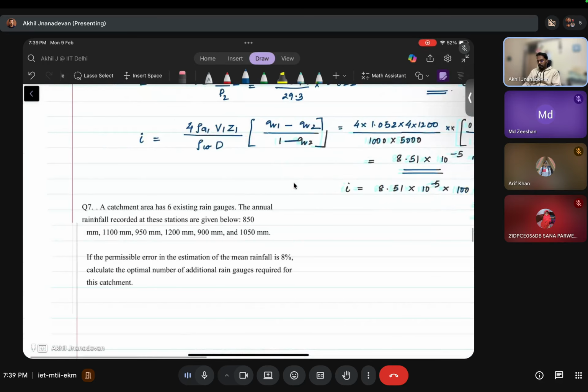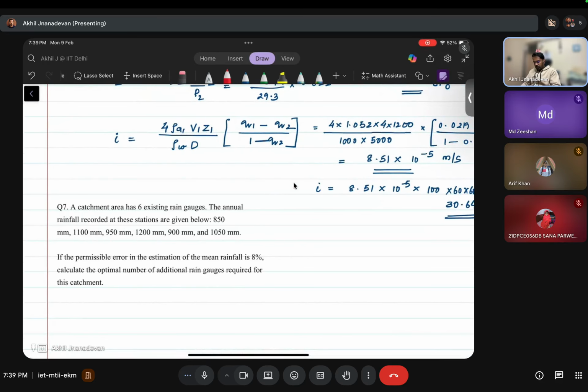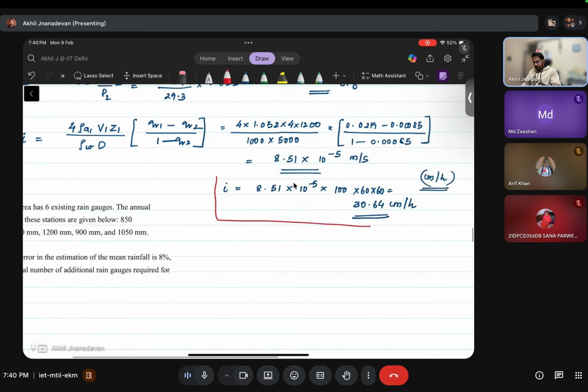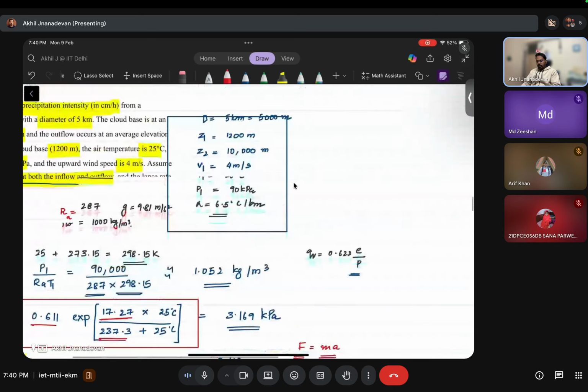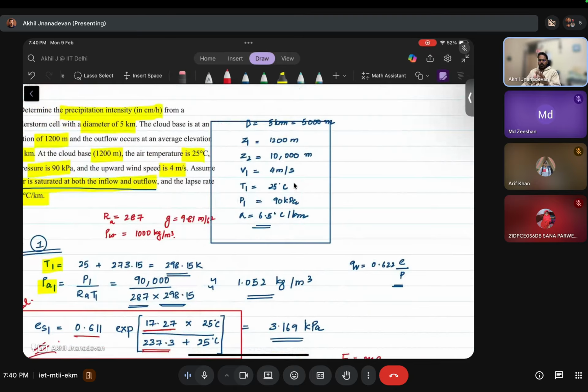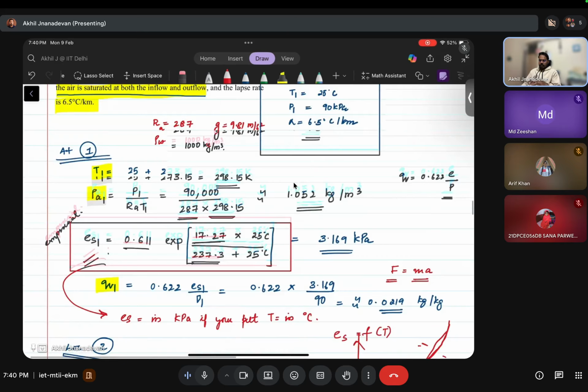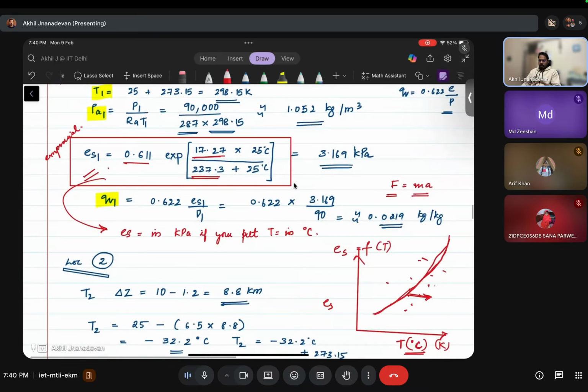The only thing you have to keep in mind is this particular pattern in which we solve it. We will always be given the atmospheric parameters at one particular location, so you should know how to find them for some other elevation. That is clear because we have the lapse rate, the gas constant equation, the pressure equations, everything. And if the condition is saturated, we can also use this empirical equation and come up with all these parameter values at different elevations.